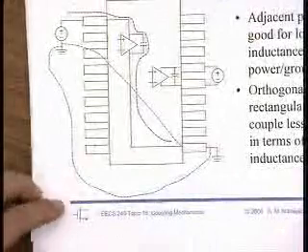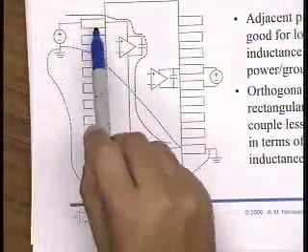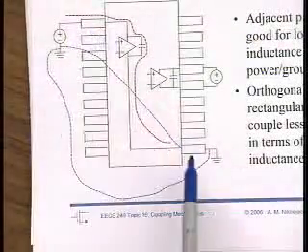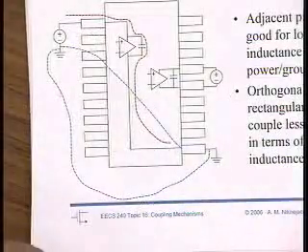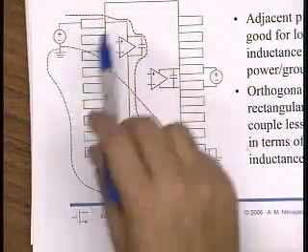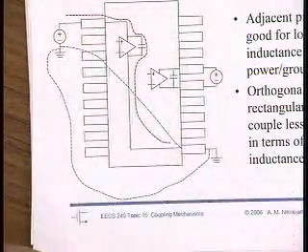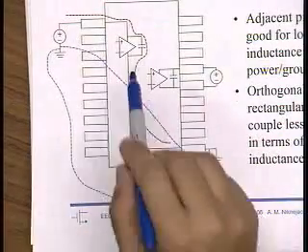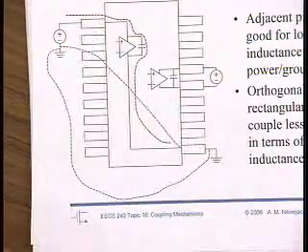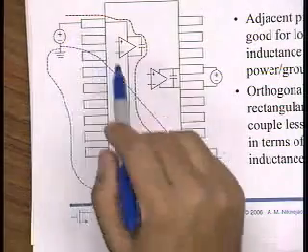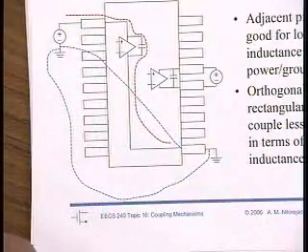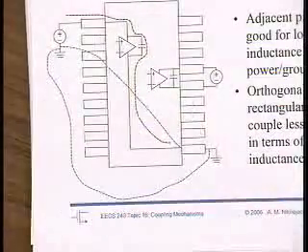In the inexperienced case, we could see that they've selected this pin for VDD and this pin for ground. And it's actually kind of funny, because in the old days you could buy chips that always had VDD and ground in these locations. And it's probably the worst choice for VDD and ground. It was standardized in the industry, so every chip you got had VDD and ground here.